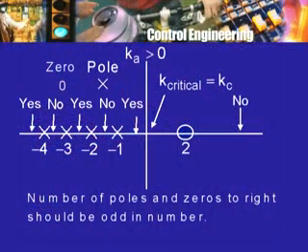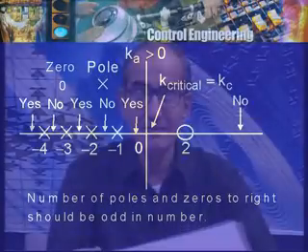This is one more rule which follows almost immediately from our knowledge of polynomials. If you think of the example that we had taken, I had said that the root locus will have a branch which will cross the imaginary axis, the j omega axis, and therefore one of the roots of the characteristic polynomial will become 0 for some value of k. So this is called intersection with the j omega axis or with the imaginary axis. Now there is a method for determining the value of k for such intersections and the corresponding location of the intersection. I mentioned earlier that there is an algorithm or a procedure which was given by Routh more than 100 years ago. Using that, one can find out the intersections of the root locus with the j omega axis or the imaginary axis and the value of k corresponding to those intersections.